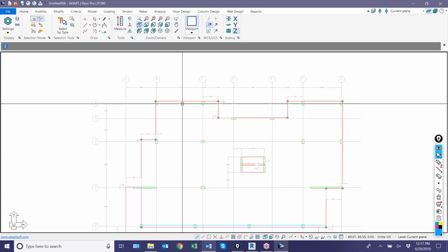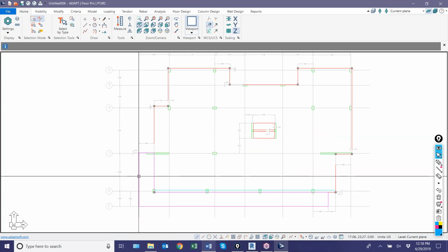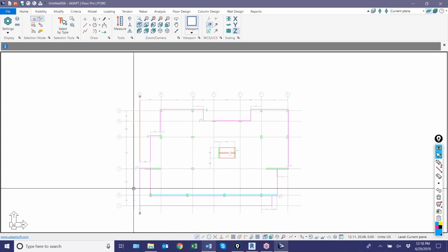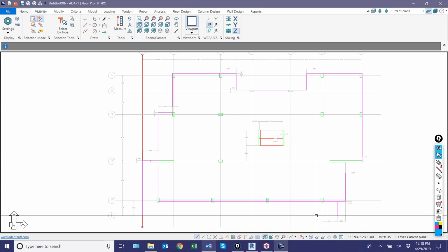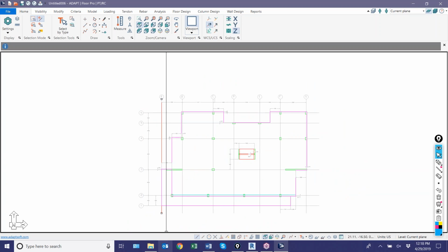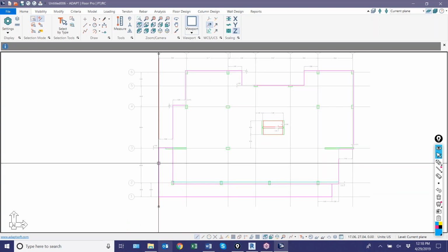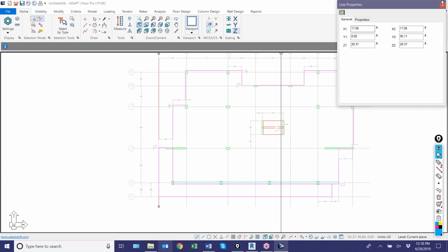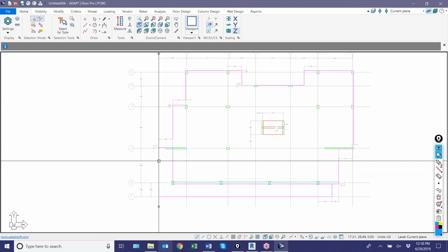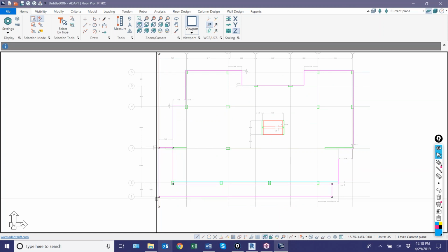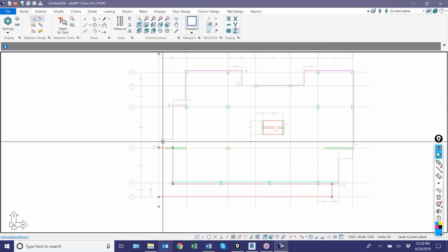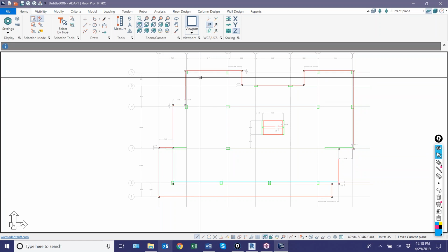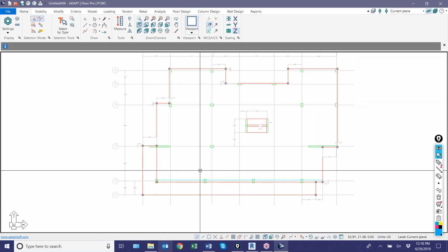So I'll select, let's say, the slab polygons first. Notice if I select that slab edge, I'm trying to select this balcony, it selects the grid line. And I say, well, that's not good. I want to select the polygon. And again, it continues to select the grid line. So if you press on it once and press tab, it will actually toggle between the two. So there's the polygon, and then I'll press control and select the other polygon, and now I have 2 items selected.